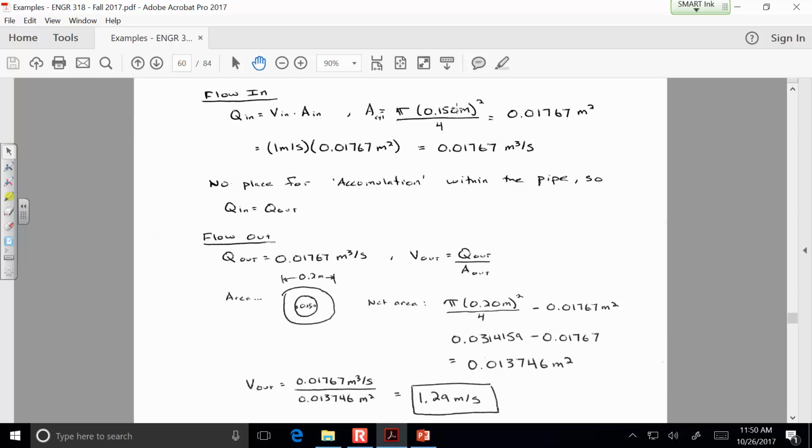And remember, the idea of flow rate isn't limited necessarily to liquids. The units of flow rate is simply cubic meters per second. And so this cylinder that's falling down, there is a volumetric rate at which it's entering this control volume. And if we know the volumetric rate that it's entering the control volume, then that's the same rate that the liquid is being forced out around the outside edges.